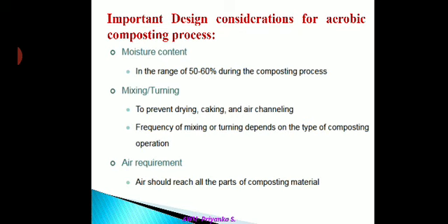Then the next is mixing and turning. To prevent drying, caking and air channeling, the material in the process of being composted should be mixed or turned on a regular schedule or as required. So to prevent drying, caking and air channeling, you have to turn it on a regular frequency. The frequency of mixing or turning depends upon the type of composting operation. So here mixing and turning also is required.